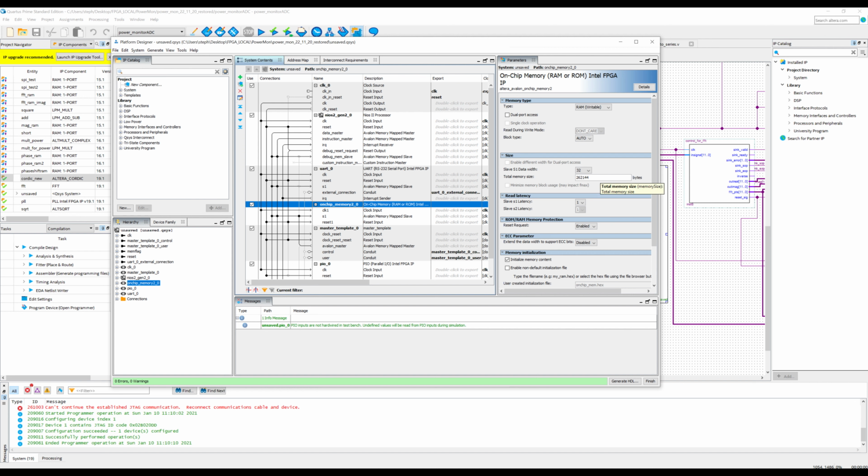This is quite large, so that's quite a significant portion of the capability of the FPGA we're using. And as I said before, if we start to run out, we can move to SD-RAM. So there is another option there if we do run out of memory. But for simple designs like this, I think using the on-chip memory is probably okay.